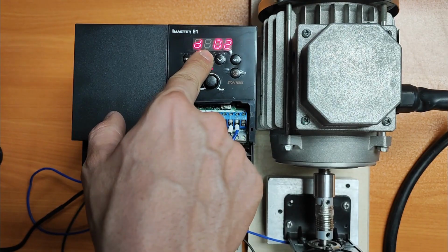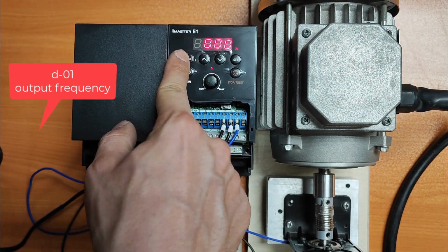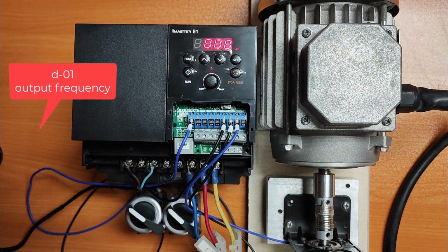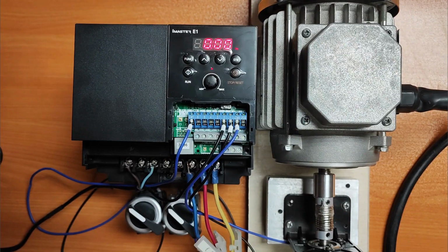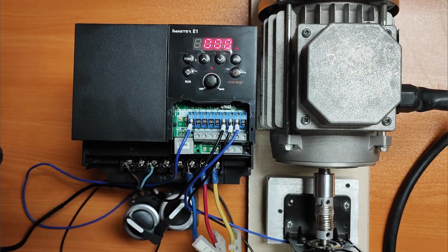Let's go back to the D parameter group from parameter number 1 so we can see the output frequency value here. Alright, now I'm going to activate one of my digital inputs. This one is for the left rotation, and this digital input is for the right rotation. First, I'll activate the right rotation and start the inverter.